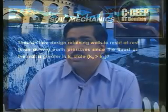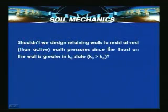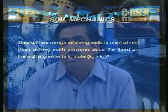But the next forthcoming slides will answer our question. Our question is: should we design retaining walls to resist at rest rather than active earth pressures, since the thrust on the walls is greater in the K naught state? Because K naught is actually greater than Ka, which indicates that the thrust P naught at the rest condition, half K naught gamma h square, will be more than half Ka gamma h square, which is the thrust due to an active state.